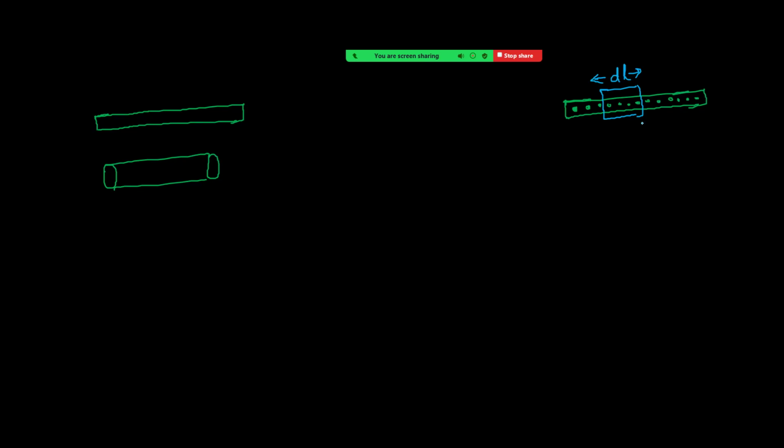So what happens is the resultant field will be only parallel to the sheet and uniform. Okay. So here what I am taking is a loop like this. Here current is now towards us. So keep the thumb of the right hand towards us, curl fingers. Now the curling fingers are anti-clockwise. That's why I'm taking here for the loop anti-clockwise as positive, like this. Anti-clockwise. Now see what happens. Since current is outwards, below this one, field is right side, above field is left side.